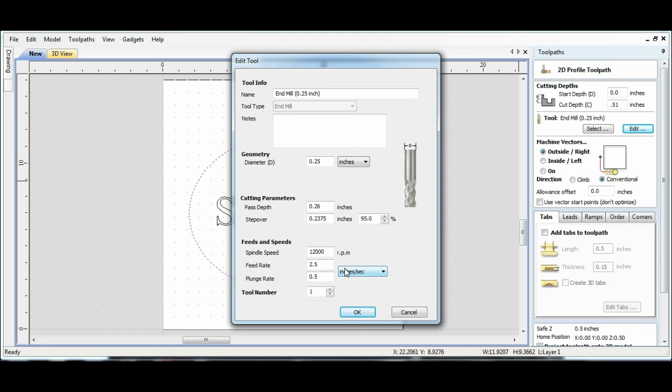And if you have any questions about these, you can always Google it, or you can ask me or anybody walking around that knows anything about the CNC machine. You can be like, hey, I'm cutting out this oak. I'm going down 1/2 of an inch. Is 3 inches per second good? Or, we'll dial it in a little bit better for you. But that's a long conversation. Spindle speed versus feed rate versus the bit you're using versus the material. It all changes. But don't let that confuse you, and don't let that scare you away. There's a wide range that you'll be safe.